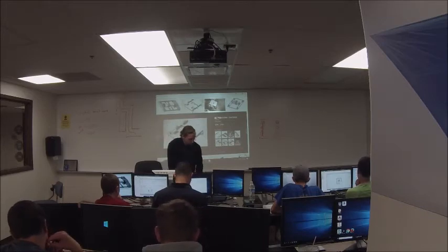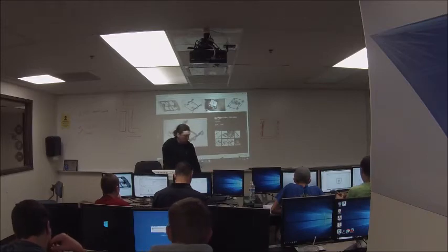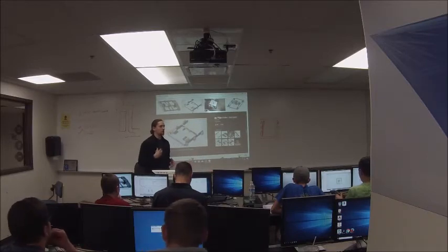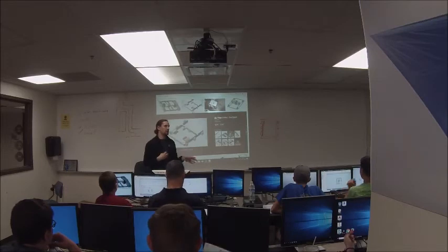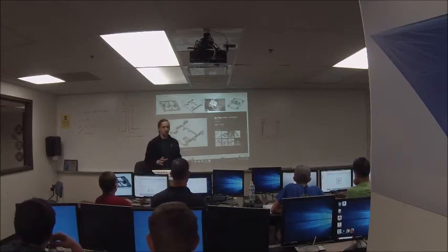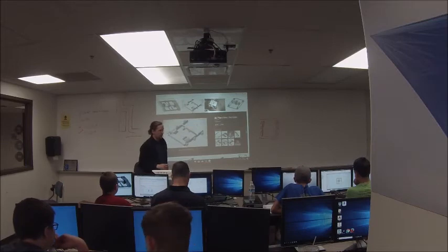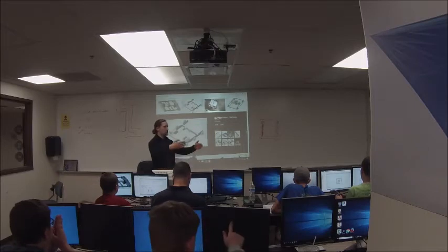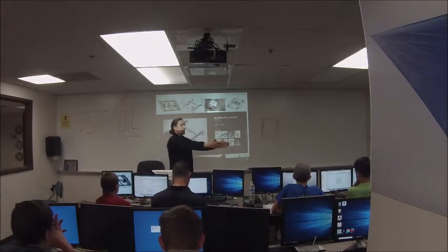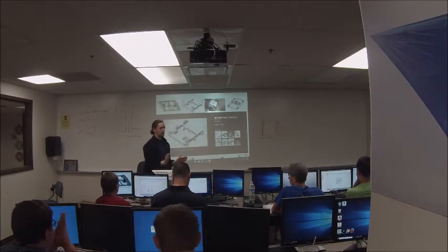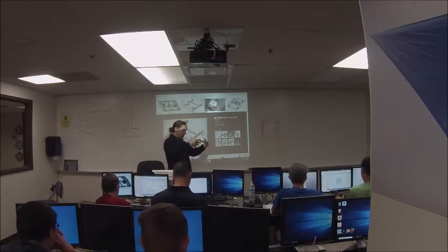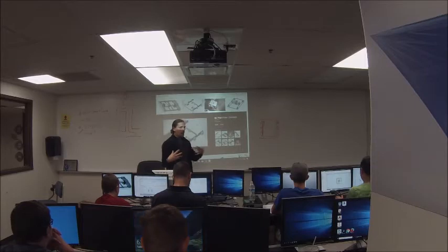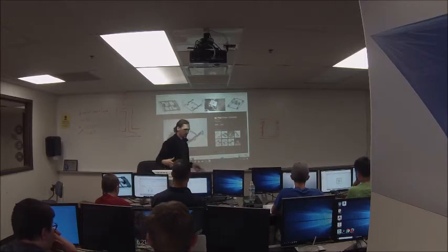There is also a version of, well, it's not a version of H drive, but it's a similar concept. A lot of people call this drivetrain holonomic, although holonomic is actually a general term, and all of these drivetrains are holonomic to a certain extent. Basically, you take an Omni wheel and mount it at a 45-degree angle on each corner of your robot, and you drive it similar to a Mecanum drivetrain, where you drive each one at different speeds. Because they're at angles and they're Omni wheels so they can slide sideways, you never get in a bind where the wheels are fighting each other. They all work together.